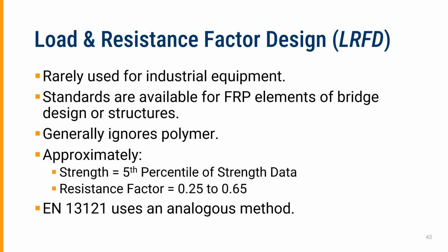In some cases, it generally does not accommodate chemical environments, so it's really only looking at mechanical loads and mechanical stresses. There are ways to adjust that resistance factor for chemical environments. And in fact, EN 13121 kind of uses an analogous method for design that starts to work almost like a load and resistance factor design for industrial equipment.